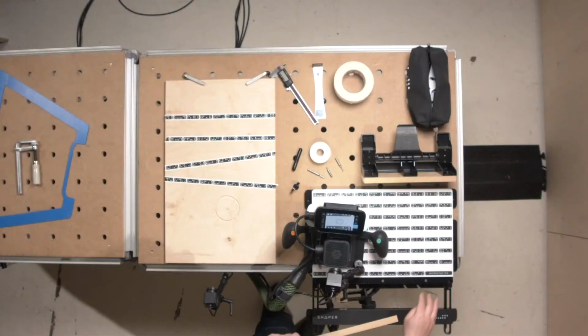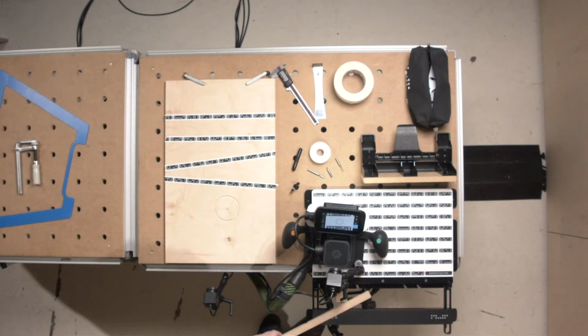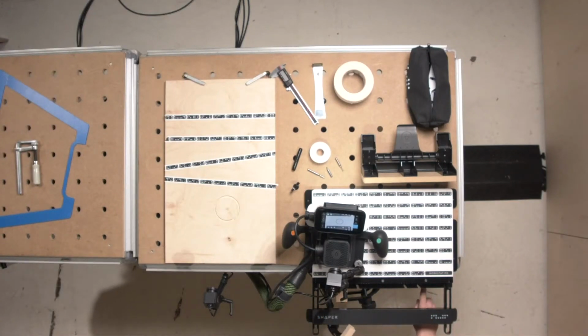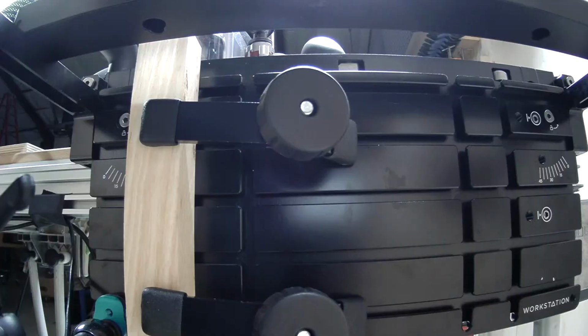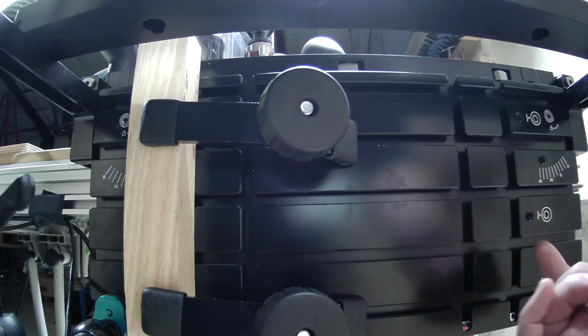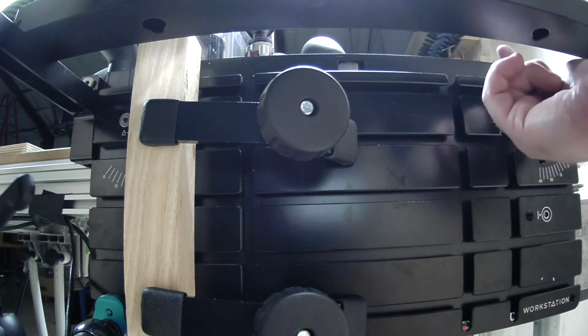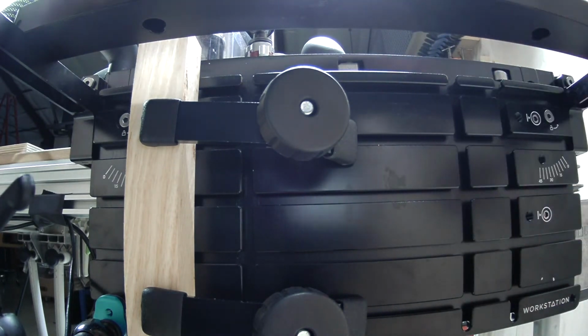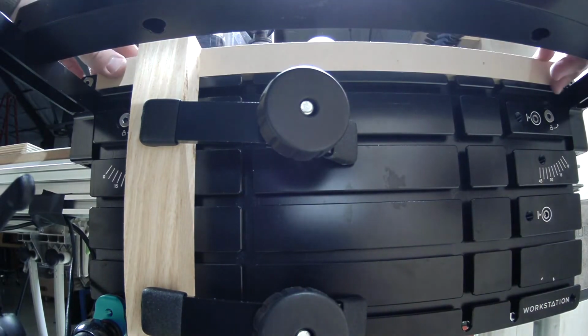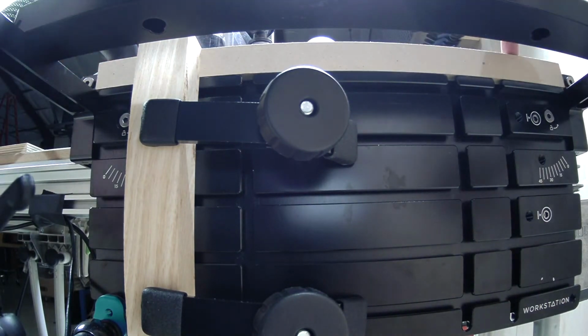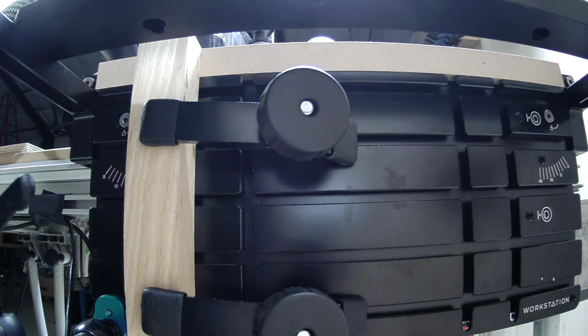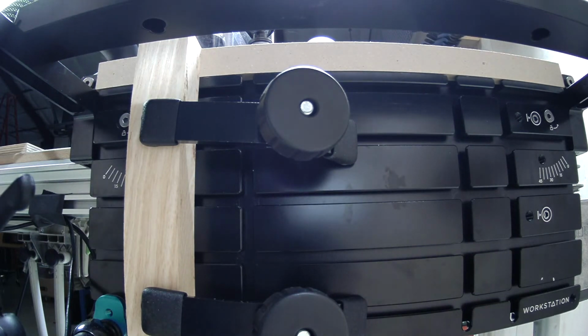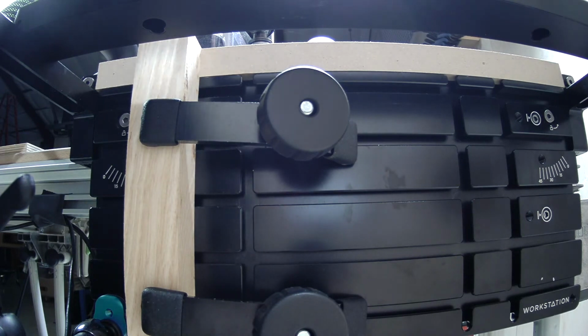And on the front clamping face of Workstation, there's 3 settings. You can actually move the whole clamping face physically either up or down. So in this case, I have it set to the middle setting, and I'm going to put my spoil board in, and then I'm going to make sure that I don't cut any deeper than that 25 millimeter spoil board, because again, then I'm going to cut into aluminum, which I don't want to do.